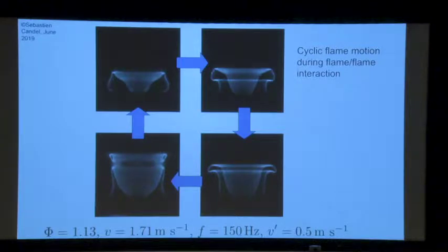Another experiment is this one. Now we have the M flame, which is stabilized on the two sides here. And you see that we produce this special shape here. The sheets get closer, and at a point, this torus breaks away, and you have a shedding of this torus of fresh reactants, and it's burning, and you get back to this situation, and it goes on like that.